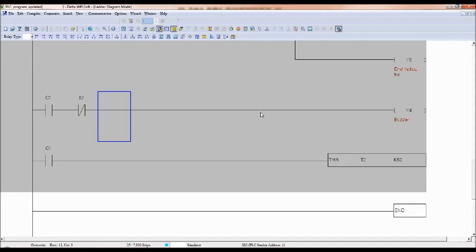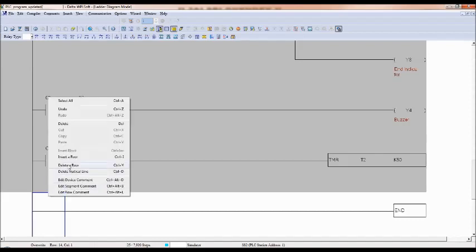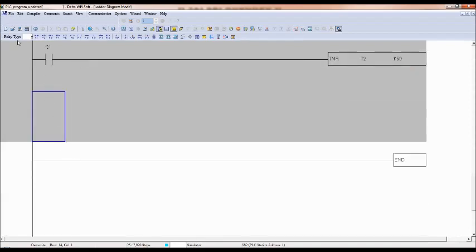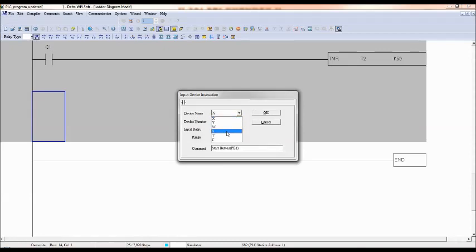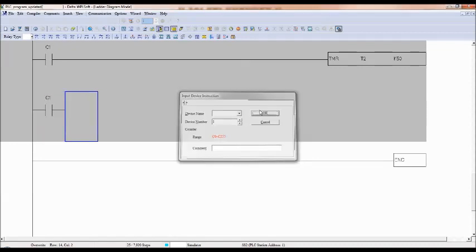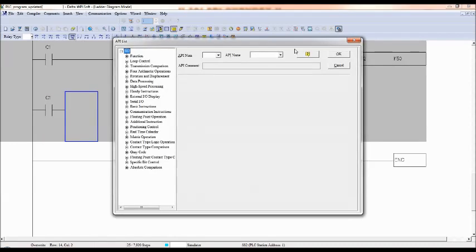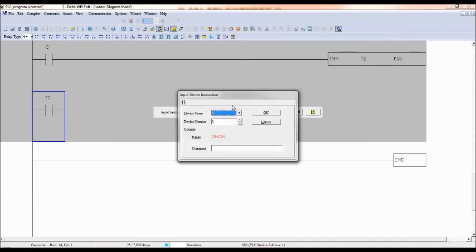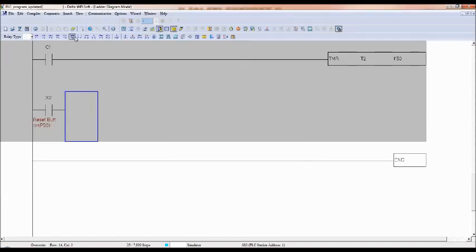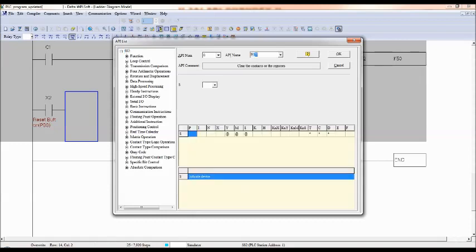There is a reset button. So using that reset button, we should reset the counter. It's not the counter itself, there is a reset button, right? There is an input X. The reset button is X2. When X2 is on, we want to reset, that is RST of C1.